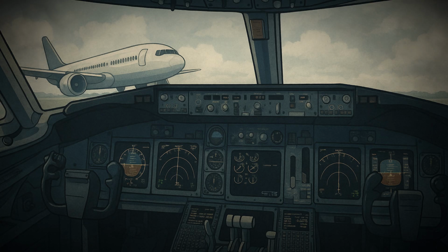Streamlining has been one of the most effective strategies for minimizing drag. From the earliest days of flight, designers learned that smooth shapes resembling teardrops allowed air to flow with less resistance. Modern airplanes are the result of countless refinements in aerodynamic design, with every curve, angle, and surface carefully tested to reduce drag. Wind tunnel experiments and computer simulations help engineers predict airflow patterns and optimize designs. Materials science also plays a role, as smoother surfaces and advanced coatings further reduce drag.